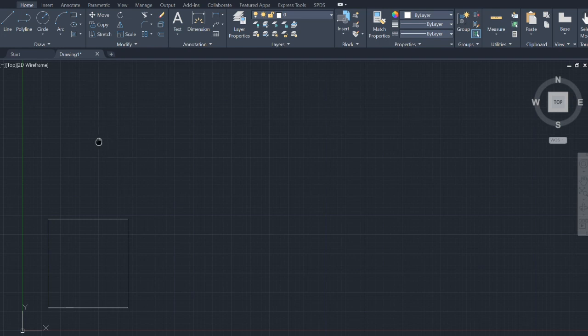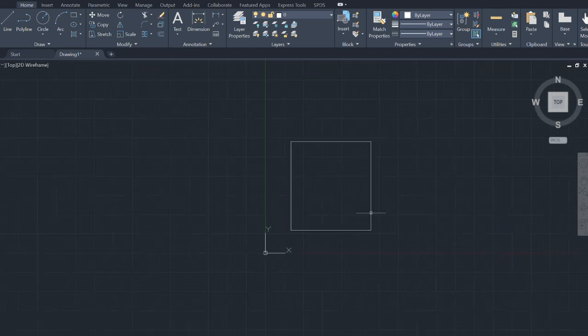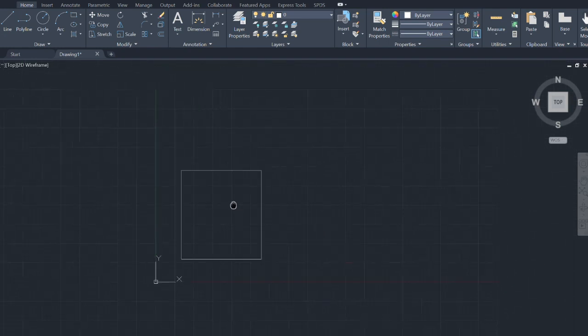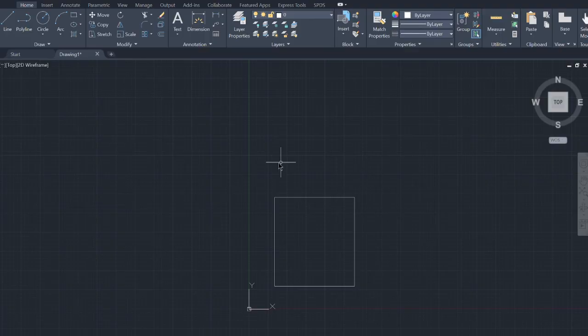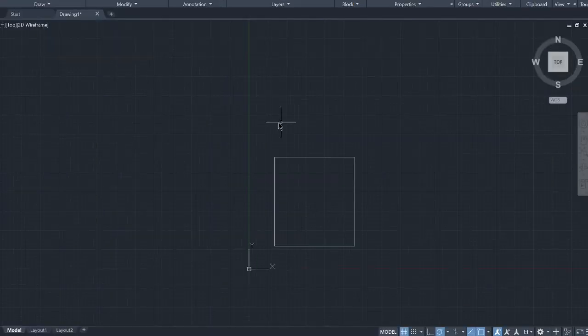Just kidding, right? But the pan, as what Ma'am Bea has discussed on the last meeting, basically, you just want to move, to navigate your drawing on whatever side you want. All you have to do, there are two techniques. First is to type pan. Or to type shorter, you can just type P and then enter.